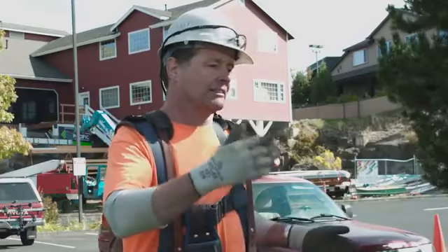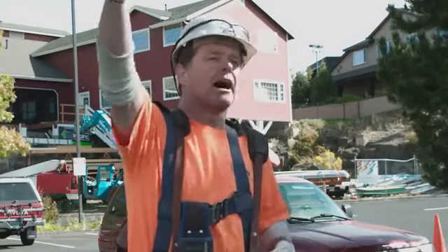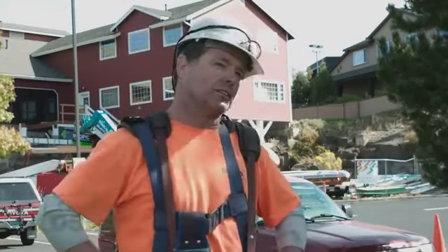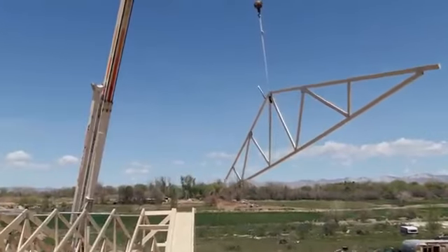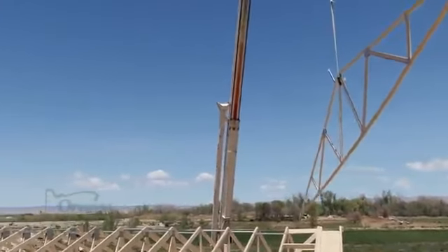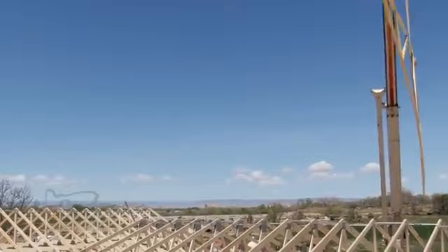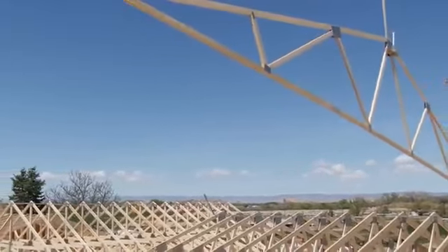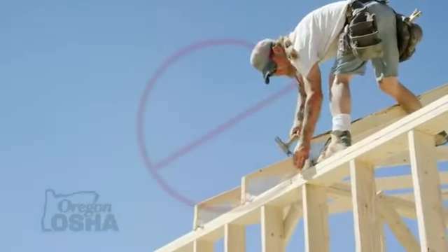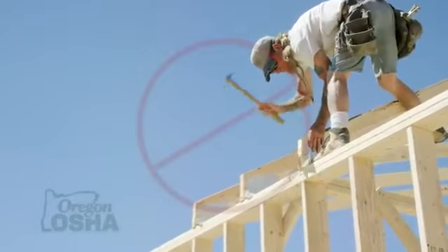Once they're braced and stood, then you can put your retractable up higher, and then you can roll your trusses. A lot of our jobs, a crane just flies one truss at a time, but that's big trusses. There's a lot of different ways of doing it. We used to always walk the top plates and roll the trusses and bend down and put the blocks in.